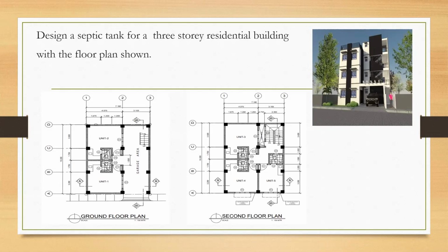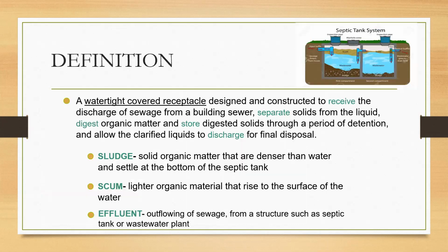But before we proceed with our design, first we should define what is a septic tank. A septic tank, based from the definition on the Revised National Plumbing Code, is a watertight receptacle designed and constructed to receive the discharge of sewage from a building sewer. So hindi po ibig sabihin na ang septic tank po natin ay magtatapos hanggang plastering works. So we should also provide or apply a waterproofing.